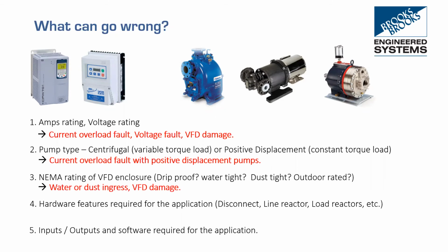The NEMA rating: if we select a NEMA 1 VFD and put it in a washdown plant, we're obviously going to have some VFD damage very quickly. So we've got to make sure that we match the NEMA rating to the operating environment of that VFD. And the hardware features, again, if our customer is expecting to have a local disconnect and it doesn't have one, and they have to add their own, they're not going to be happy about that.